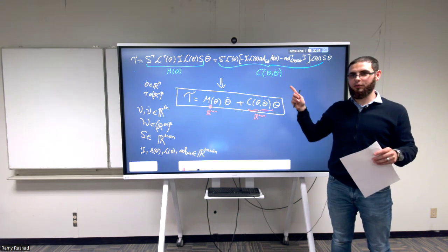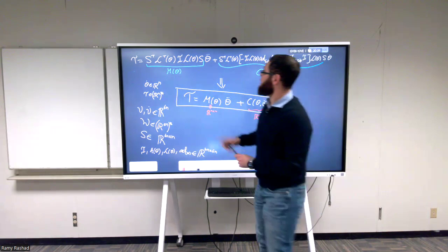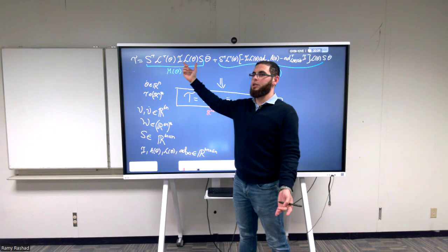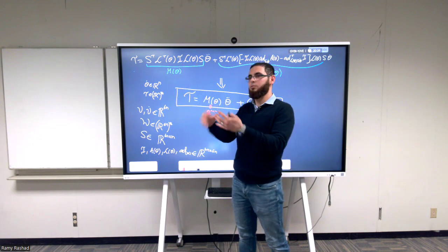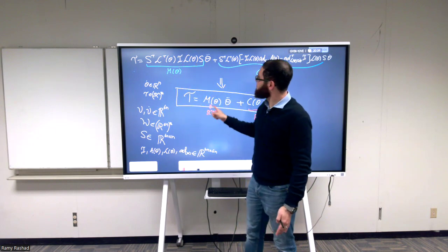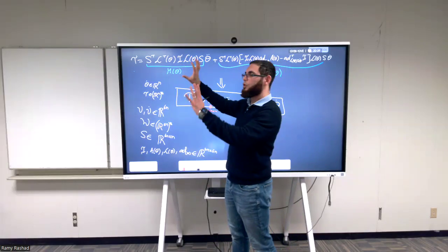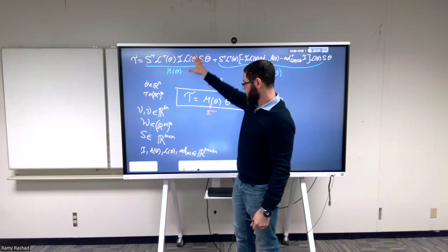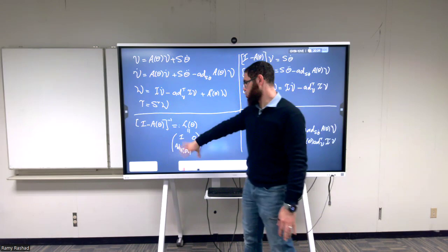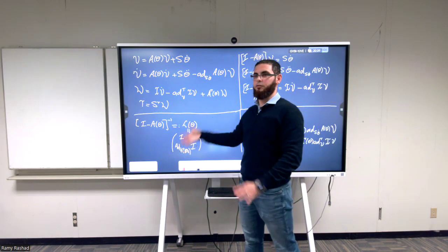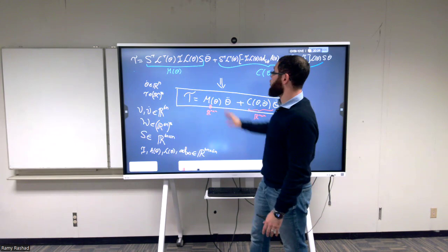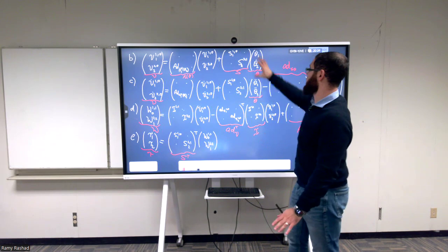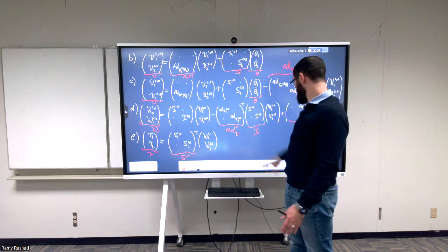Okay, the last part about the transformations. In the end, we say this is a mass matrix. And this was inertia. What was the inertia? It had mass and moment of inertia and so on, you see? So the M here is nothing else than the I, but changed with the change of coordinates. If you go back to the L, it had some adjoints in it with some extra stuff, just because we have multiple rigid bodies. And if you go to the S, there was nothing else than unit twists. So it was a bunch of twists together. So this is the change of coordinates.